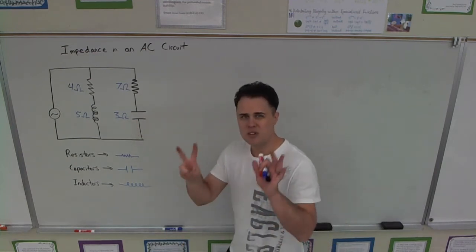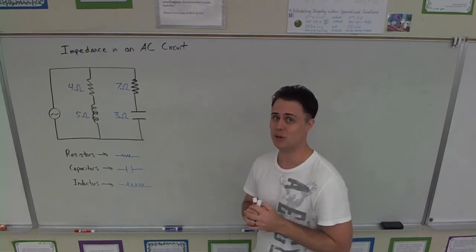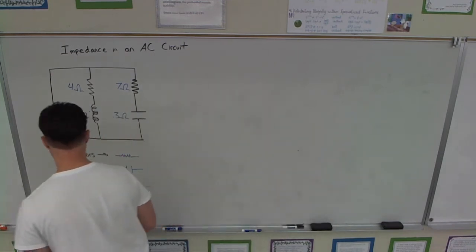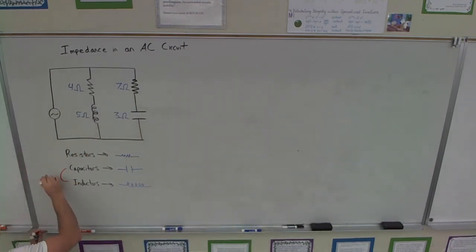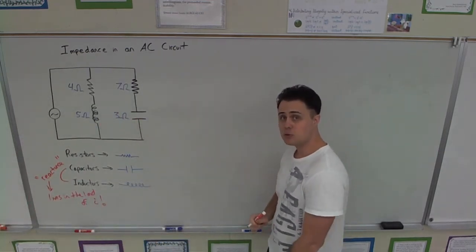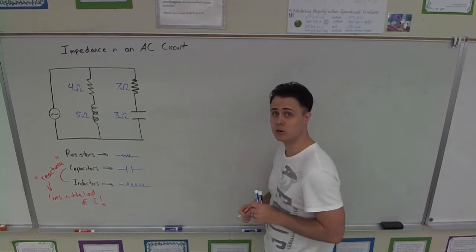These also try to resist the flow of electrons, but they do it in a different way. In fact, they do it in the complex dimension. So I'm going to group them together. Instead of resistance, it's pretty similar, but it's called reactance. So that reactance actually lives in the land of i, the land that we have just begun to explore. So you have to consider that resistance to electron flow as a complex and imaginary resistance.